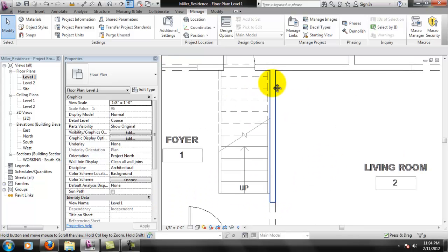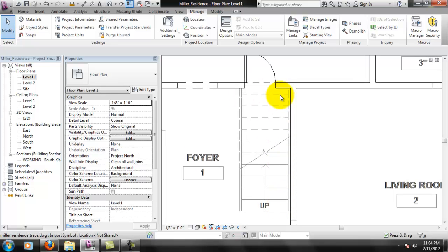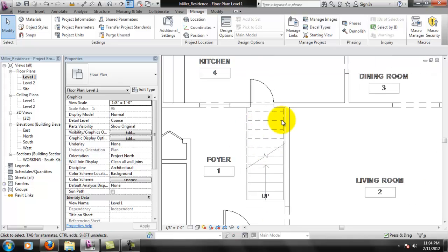Okay, so looking at the CAD plan that we have here, it's showing that we need 11. Okay, there's 11 treads here. So with there being 11 treads to get to the top, which is at 10 feet, if you do the math, that comes out to numbers that aren't necessarily code, but it's an old residential house, so these stairs are going to be a little weird when you consider the sizes that we use. They are actually kind of steep, so when we start changing the numbers, we're going to need to create our own stair, custom stair slope for this.